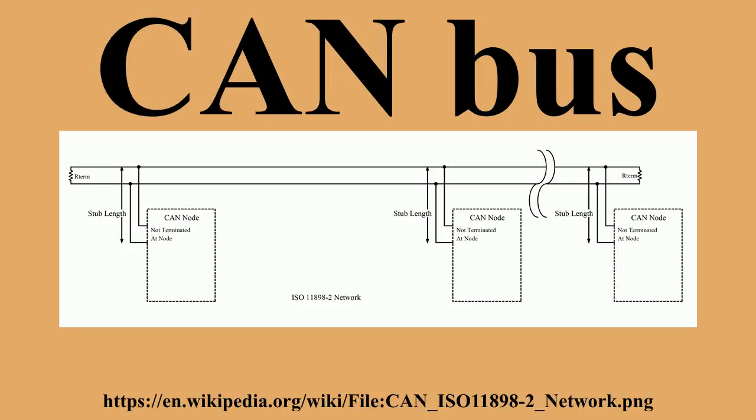When the 8th bit is transmitted, the node with the ID of 16 transmits a 1 for its ID, and the node with the ID of 15 transmits a 0 for its ID. When this happens, the node with the ID of 16 knows it transmitted a 1, but sees a 0 and realizes that there is a collision and it lost arbitration. Node 16 stops transmitting, which allows the node with ID of 15 to continue its transmission without any loss of data. The node with the lowest ID will always win the arbitration, and therefore has the highest priority.